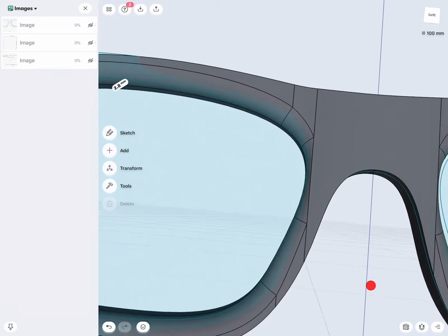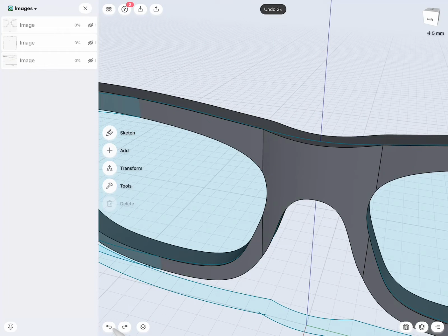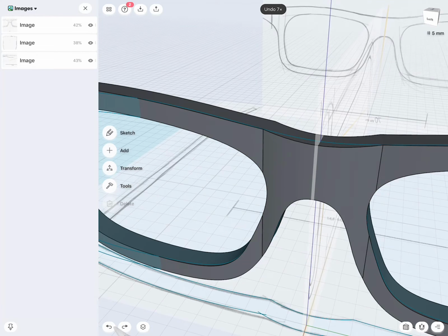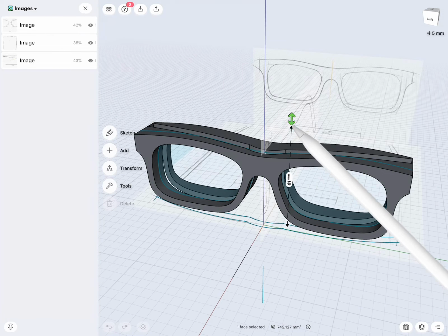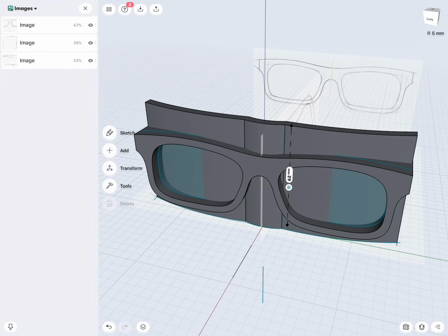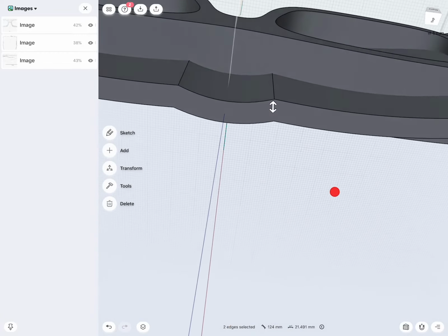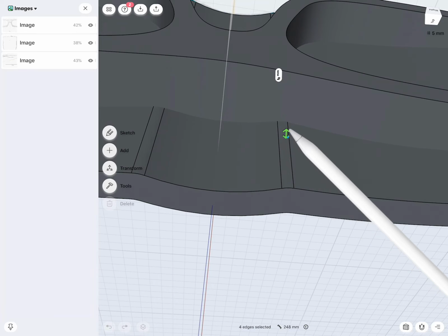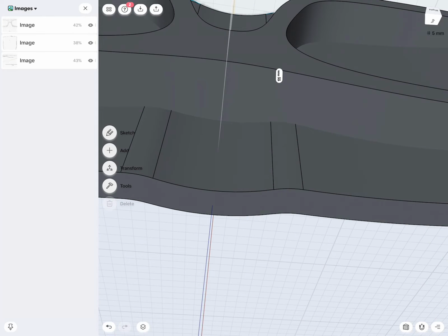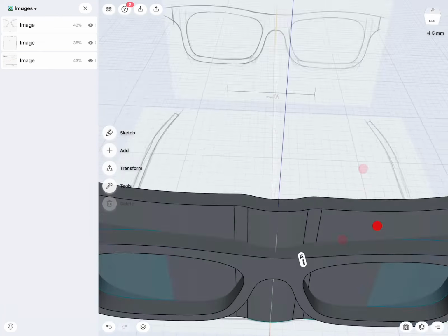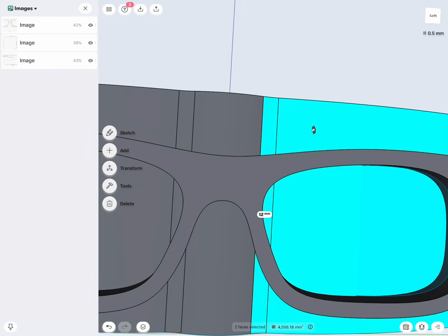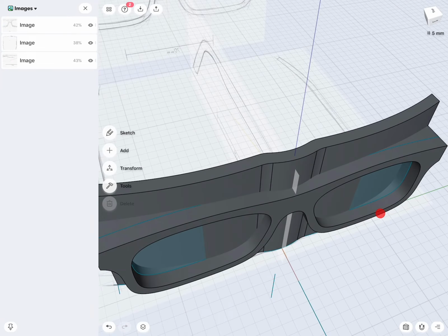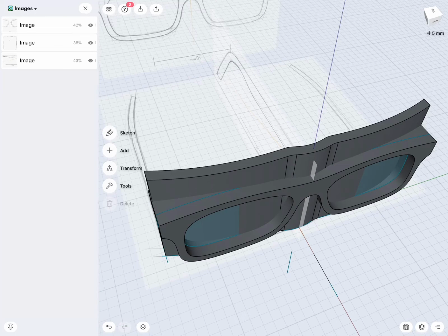But now we see this happened there, so it didn't really run perfectly through it. So what I will do instead, in case this happens, I undid all my steps. I select this, extrude it up again, and then I simply say new body. And on this new body, I will select these complete long edges and fillet them at once. Okay, good. The main reason why I do this is now when we do the intersection, I have nice and clean geometry. Before I had kind of like a faceted geometry, and I forced the modeling kernel to understand what I want. This way I have a little bit more control.